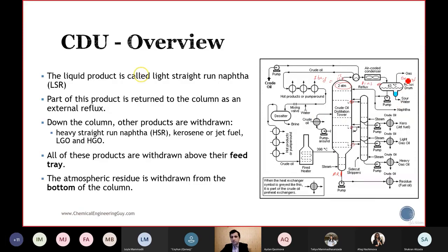And then we separate the gases here. So what we don't want. In gases, let's say there is a maximum C5 spec in gases of around 2 weight percent. What does it mean? In gases, we make the analysis, and then out of the analysis, we have the result. There should be a maximum of C5, 2%. If we have 3%, it means that we are losing naphtha or gasoline in the gases.